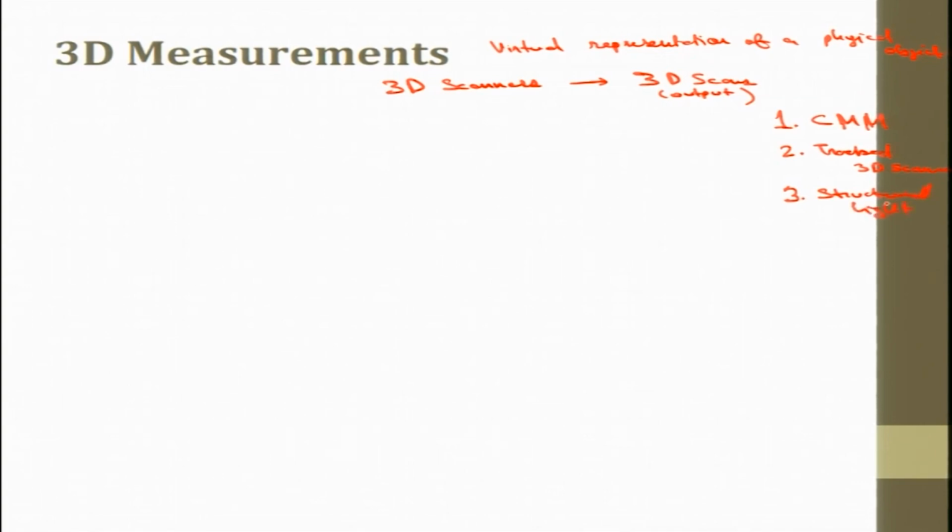Structured light scanner. By structured light, I mean that these scanners project a pattern of light onto a part or a process while it is happening, and observe how the pattern is distorted when the light hits the object. Either an LCD projector or scanned or diffracted laser beams project the light pattern. One or two, or sometimes more, sensors record the projected pattern.